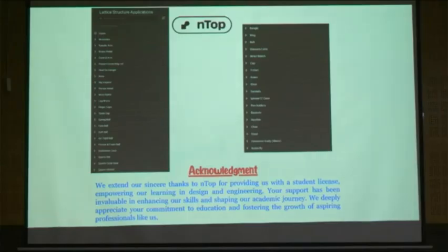If I didn't rename anything, implicit body 1 means it will go like implicit body till 1000 or something. So each one I have renamed as a separate file, like some branches. So branches body, branches original, branches lattice, like that I need to rename. If I didn't rename, you will get confusion while applying so many operations on these things. That's why, it is a good practice to rename it actually, okay?